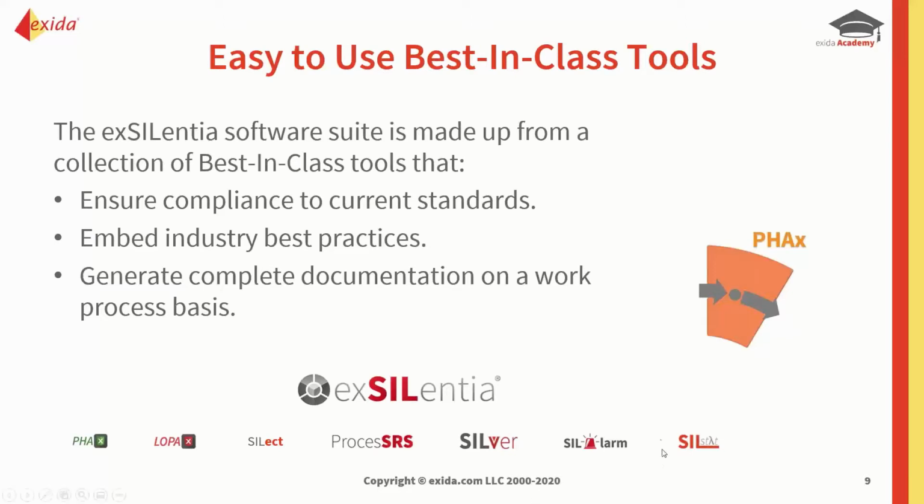And then the SILstat tool will allow you to do your performance monitoring during normal operation. So you can pull all the information from the Verify tool regarding the SIFs, the actual instruments, the proof tests themselves, and then you can run the proof tests remotely in a handheld, which links back to the SILstat tool. So everything is available through the database.